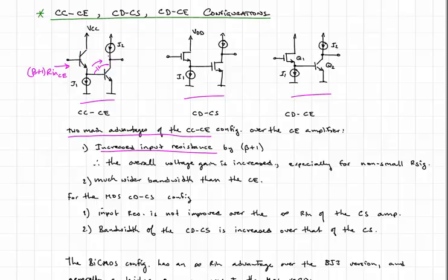So you can imagine the higher the frequency that you are trying to drive the base, the faster the collector voltage is slewing up and down, and therefore the greater the current that will flow through this capacitance, because the reactance of the capacitance goes down with frequency. So eventually the current flowing through that capacitor will be substantial enough that it will take a significant amount of current away from the base and effectively reduce the voltage gain of this output transistor.